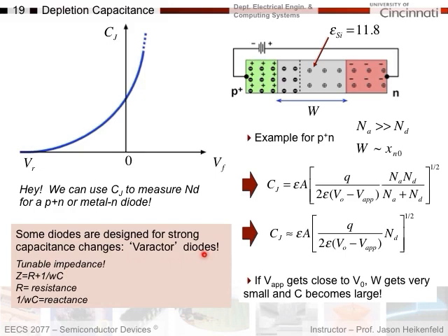You have to have the exact right capacitance. Well, you put one of these tunable Varactor diodes in there, then you are able to tune this thing in real time so it hits its sweet spot, and it's propagating an RF or microwave signal with maximum efficiency.